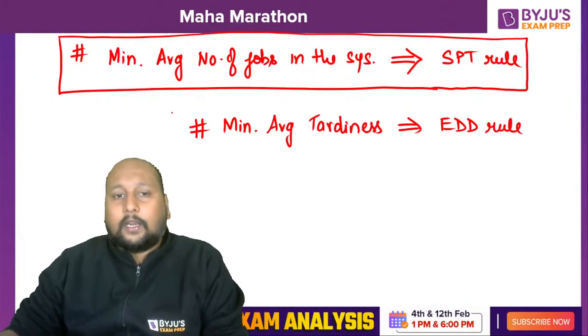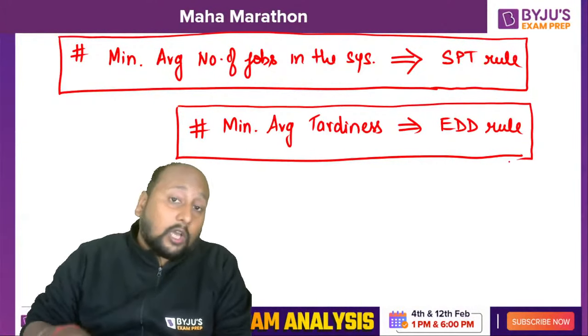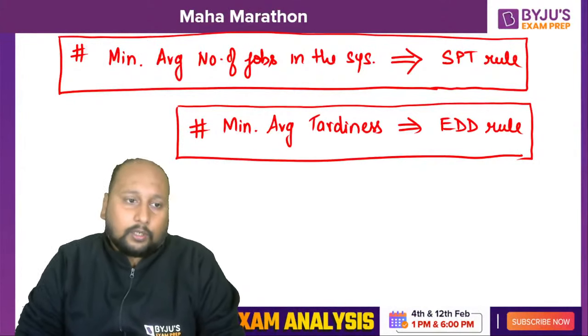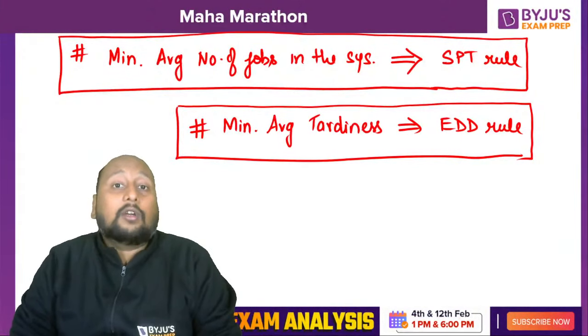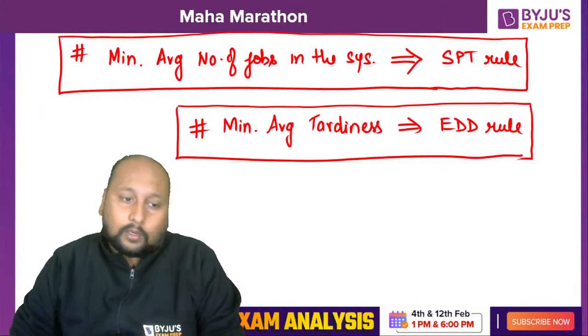Very important: if in the examination they do not mention which rule you have to apply, you have to understand it from these two pieces of information. If the question asks for the minimum average tardiness, by default you use the EDD rule. If it asks for the minimum average number of jobs in the system, by default you use the SPT rule. Is this clear?